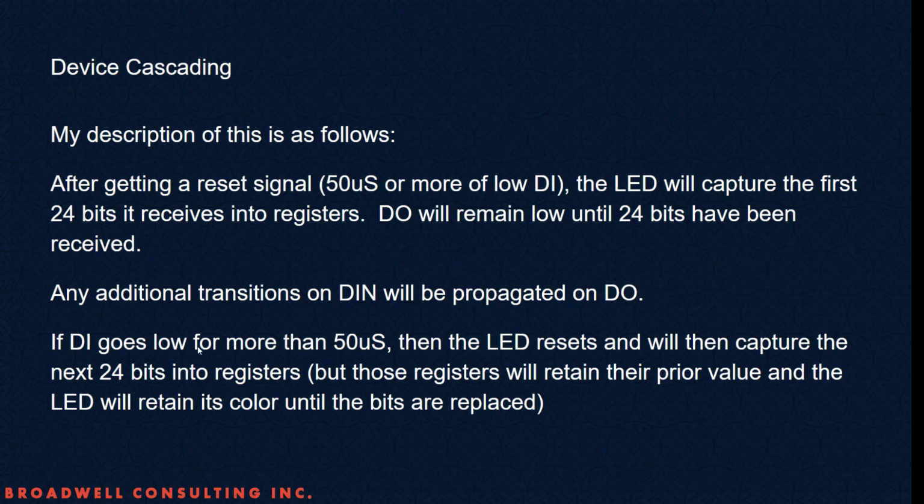If DI goes low for more than 50 microseconds, then you go into this reset case, and it'll capture the next 24 bits into the registers. But the registers will retain their prior value, and the LED will retain its color until the bits are replaced.